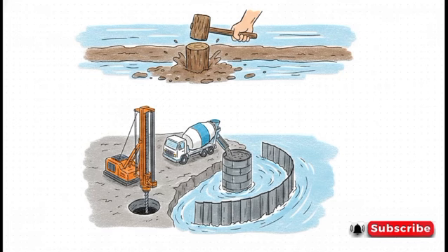Now, what if we tried that today? Well, modern construction regulations definitely wouldn't let us use wood on a riverbank. To conquer that same riverbed in the 21st century, we'd need heavy drilling machines to bore out 600 holes, each 1.5 meters wide and 150 feet deep. We'd have to drive massive steel piles into those holes, fill them with specialized water-resistant concrete, and then cap the whole thing with a concrete slab that is 5 meters thick.